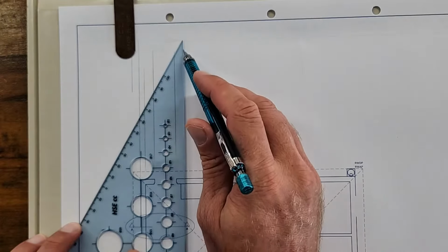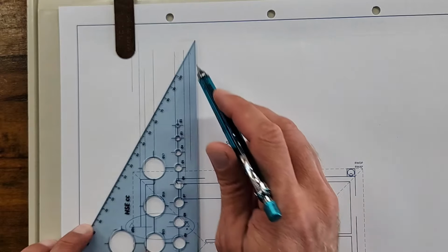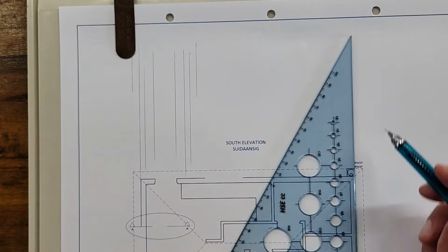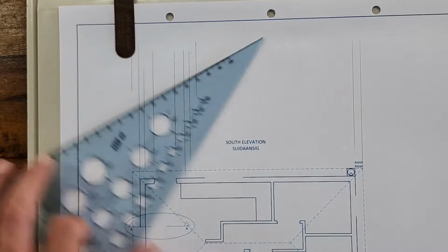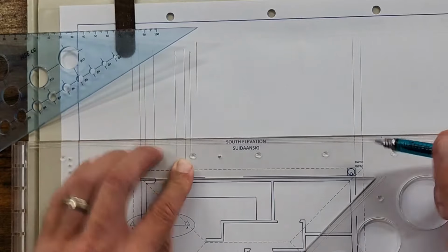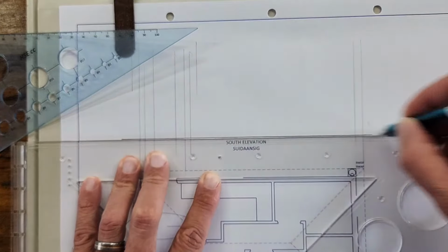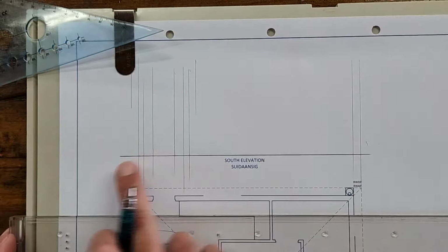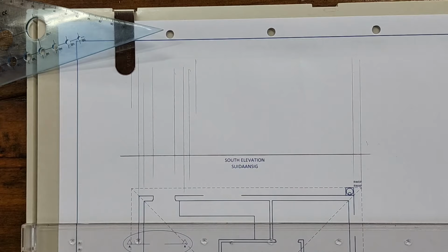Inner wall at the bottom. And then again a roof overhang, so just on the top there to help me out. We'll do the window last. Outer wall roof overhang. Alright, I'm going to put this floor natural ground level line right at the bottom as close as we can. The previous time we did this, we gave us too much space and our roof didn't fit in. So make sure that first line is right below, on top of that south elevation.